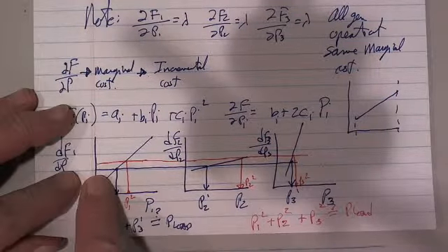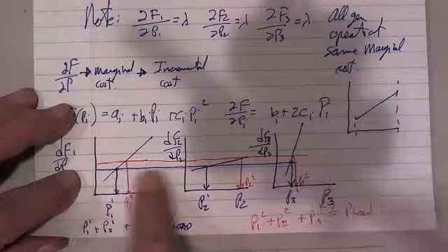And then you will have equal incremental cost on those three generators. Later on, we will show you that can be formalized into what is called a binary search, and it's very powerful because it takes care of all the limits in a very simple, elegant manner.